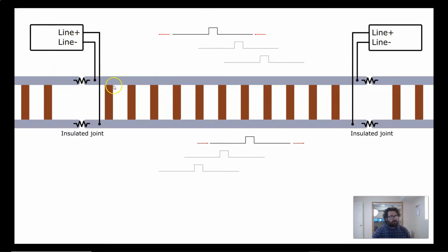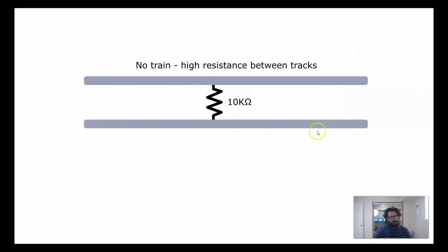So these coded track circuits are bidirectional, and that's why I've shown pulse being transmitted from left to right here, and right to left here. I've also shown 3 copies of this waveform being transmitted, and that indicates that when these coded tracks transmit signals, they're going to transmit them redundantly. So if you want to transmit a code 2, it's going to be transmitted redundantly 3 times before that's accepted on the other side.